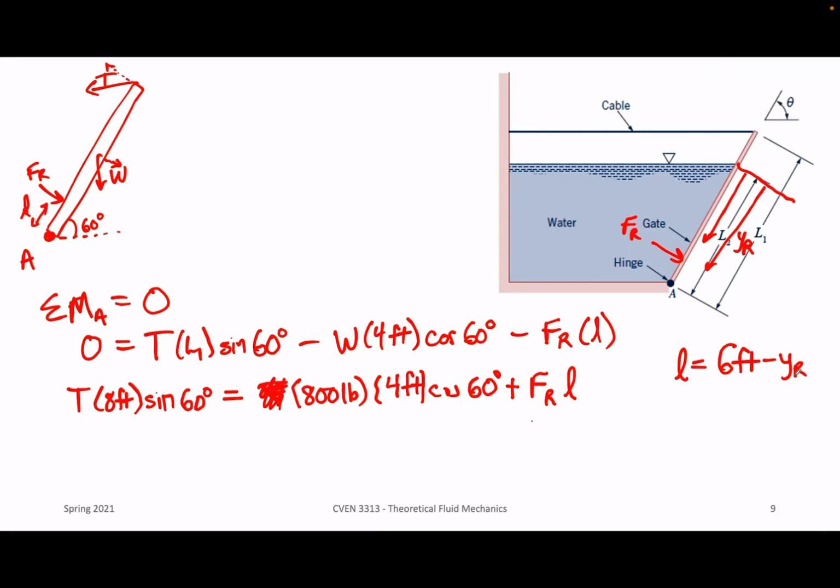Do you mean 8 feet rather than 6 feet right there? No, I do mean 6 feet, and the reason for that is that the water is only interacting with 6 feet of the gate. So that's a good point. I'll go over that on the next slide. In fact, that's why I brought this out, because I wanted to make sure that we had an understanding about what is 8 feet and what is 6 feet because of the interaction with the fluid. Yeah, great question, Brayden.